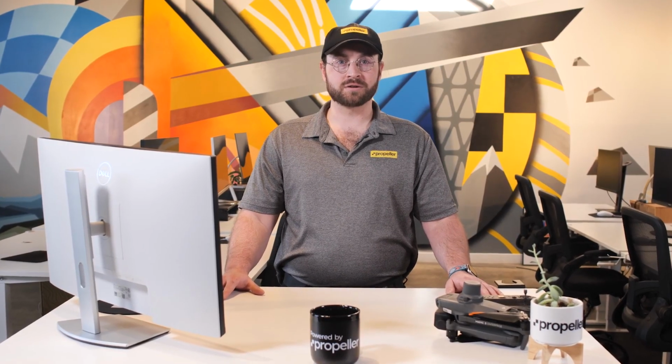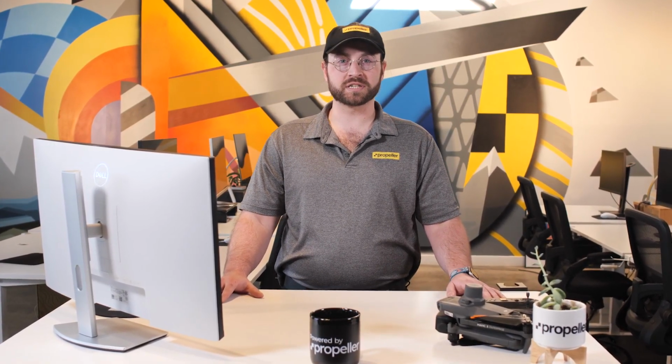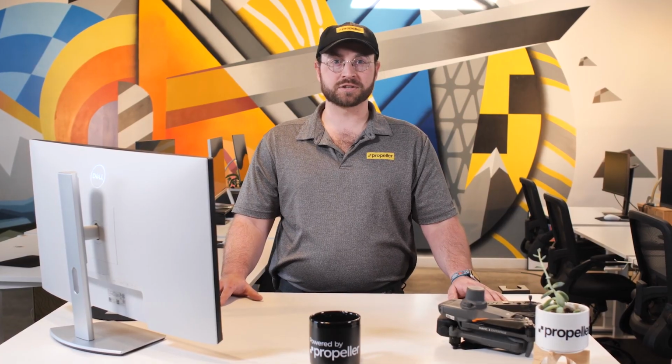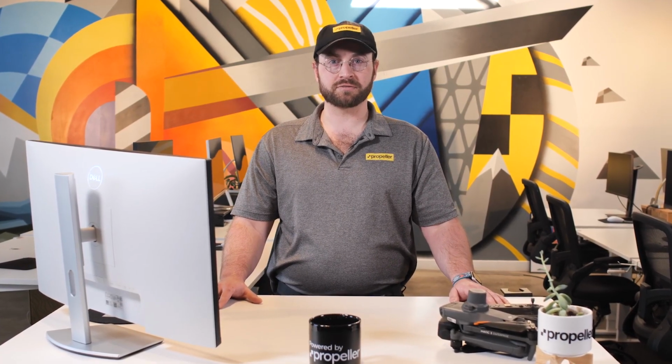We understand that surveys are not a one-time thing, and so if you need to fly a site again with a different payload or adjust a previous flight, you can easily access your saved missions. Simply select the flight route from the DJI Pilot 2 home screen, and all the saved missions will appear. You can select one of these to refly the mission, edit the mission and camera settings, delete the missions from the RC, or export them to an SD card.